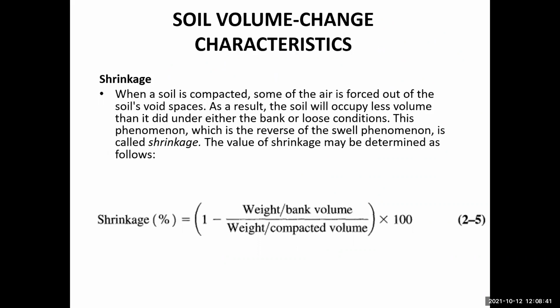And then the shrinkage. Shrinkage is when a soil is compacted, some of the air is forced out of the soil's void spaces. As a result, the soil will occupy less volume than it did under either the bank or loose conditions. So this phenomenon, which is the reverse of the swell phenomenon, is called shrinkage.